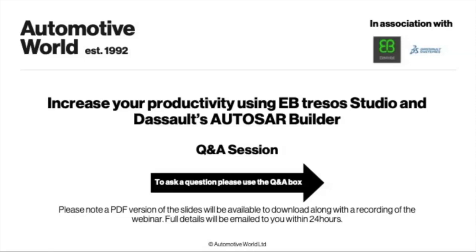And is it possible to emulate the whole ECU on Windows or Linux, for example, for software-in-the-loop testing purposes? Mm-hmm. So on the AUTOSAR Builder side, you could also emulate the whole ECU. We support basically three levels of simulation. The first level, which we call the virtual functional bus level, takes the software components into account, including the OS and the RTE. This is what we call the VFB level simulation.